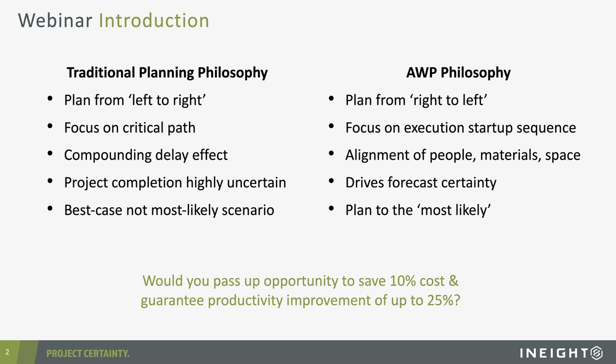And then from that defined completion date, we literally work backwards, defining the construction or the execution scope. Then we look at, well, what and when is needed in terms of fabrication in order to satisfy that construction. And then taking that a step further, what is needed and when is it needed from an engineering perspective in order to feed into that procurement, which then feeds into construction.